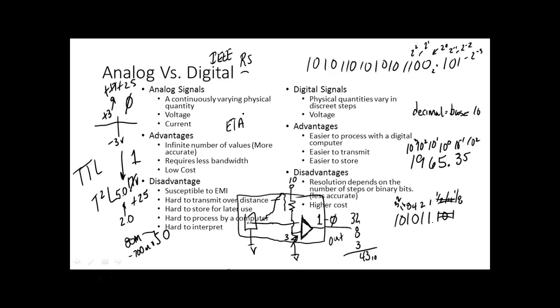It's a serial technique. Serial is one of the main methods that we use to transmit information. And what advantage does serial have over parallel? When we send digital information, what's the advantage of serial over parallel? So right now I'm sending you information. Am I sending it parallel or am I sending it serial? I'm sending it serial. Down there on the crystal line, those are serial cables. Those are on the Amatro line, which is using something called Profibus, which is serial. The big advantage of sending digital information serially is it takes a lot less wires.